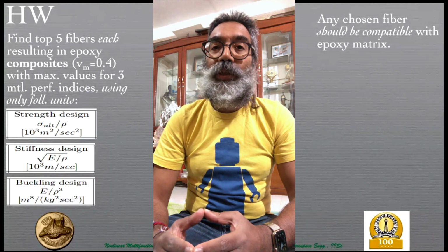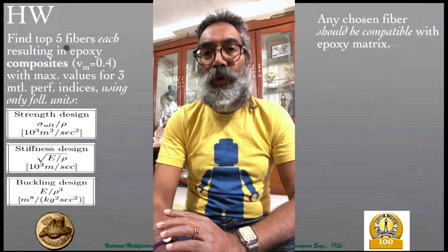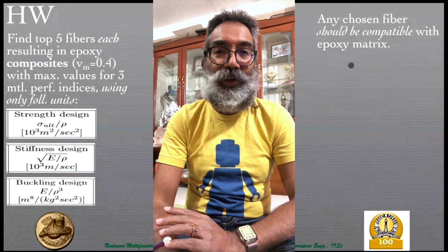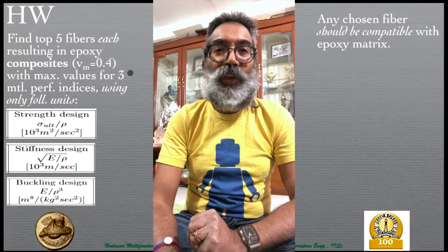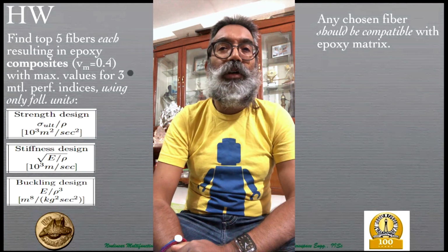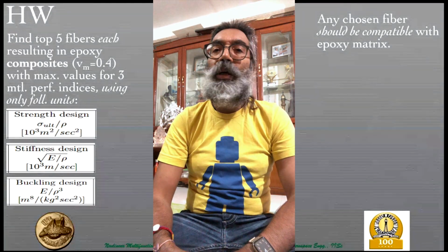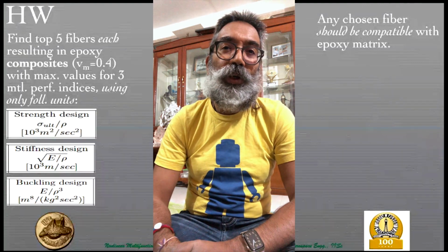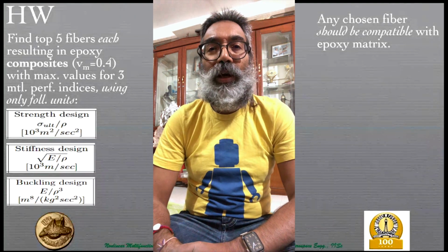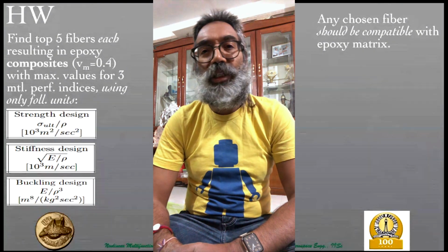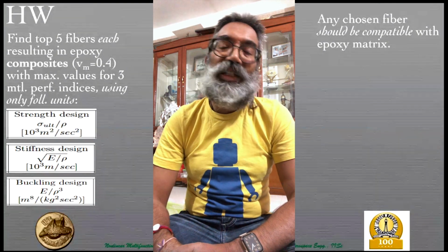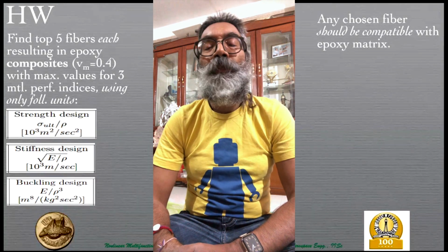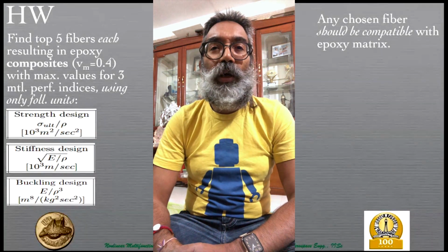The other important thing is, when you choose a fiber, make sure that it is compatible with the epoxy matrix. In other words, if it's chemically reacting with epoxy or does not mechanically gel with epoxy, then it's not a good fiber to use, because the interface between the fiber and the matrix will become the weak link, and stress transfer would not take place between the fiber and the matrix, and vice versa, and therefore it would not act as a composite.